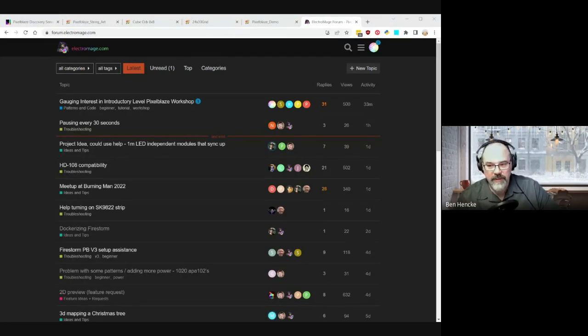And it's great for anything that you're dialing down a little bit. So if you have a piece that you don't need to be blaring at night, you can really, really dial it down. On the NeoPixel style LEDs, those will go down fairly low, not quite all the way, but then they start to lose their ability to blend colors, and you'll see things like the red is either on or off. It's either red or all of a sudden it's yellow. There's no real blending once you start to really dial it down quite a bit. So there's some advantages there.